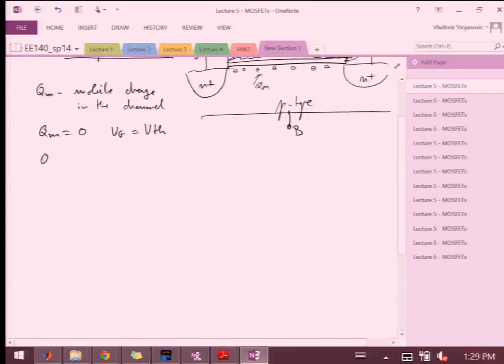Okay. And then, if we use the capacitor model, QM of VG is going to be some capacitance times any excess voltage on top of the threshold. As we start inverting and attracting the electrons, we know there's 0 of them at threshold, but anything after that will contribute to the charge. And so that must be Vg minus V threshold.